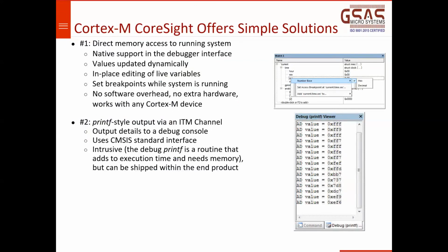So this is already explained and discussed in detail. This is just a pictorial view of it. So you can directly modify variables in the memory window. Then we have this printf style of information. This is an example which my colleague will run and show you at the end of this presentation in real time. So you can see here the ADC value through the printf viewer.